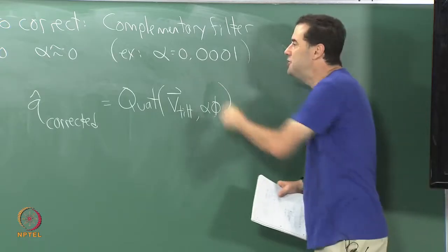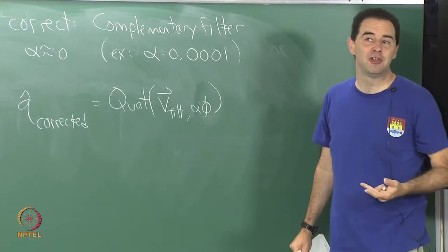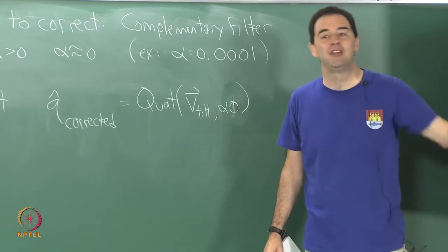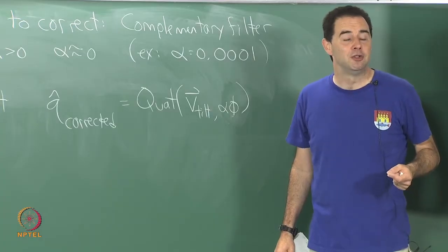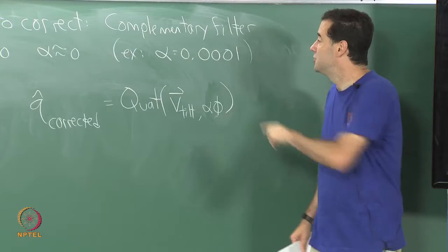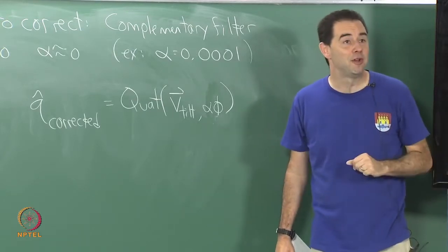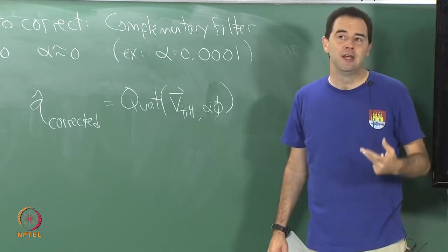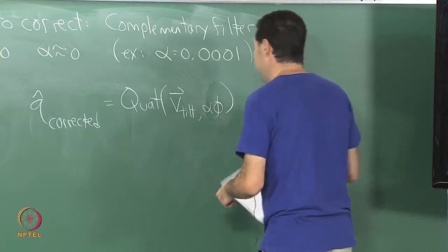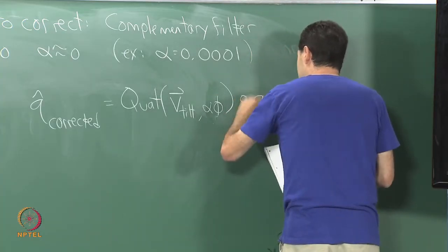But this alpha needs to be large enough so that it's applying the corrections fast enough to compensate. One of the things we did was perform experiments with a robot moving the sensor through space at different angular velocities to determine upper bounds on the maximum amount of drift error that could occur, so that we could set the coefficient large enough to overcome that. Luckily, as I said, it was still within thresholds so that it did not seem perceptible or sickening to the user. So we got very fortunate with that. We apply this correction to the previous estimate, Q hat.